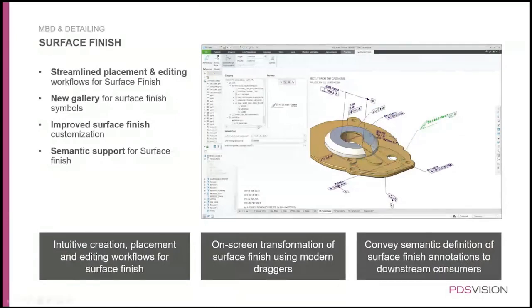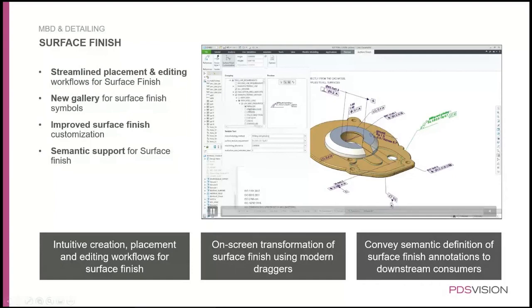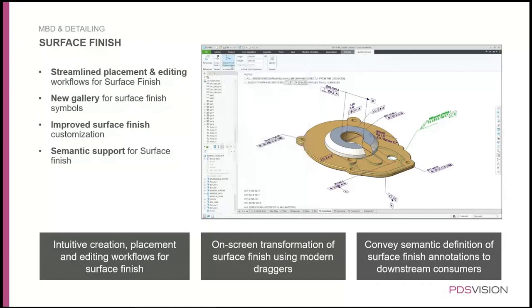This simply means that when you have applied a particular notification in here, we will also collect all the surfaces that are affected by it. So it's not required that you put the same symbol 55 times in here. One symbol is enough, and then you can collect the surfaces where it is applied. And you can ask it vice versa, click the symbol and ask what's affected, and, the other way around, what is affecting this symbol as well.